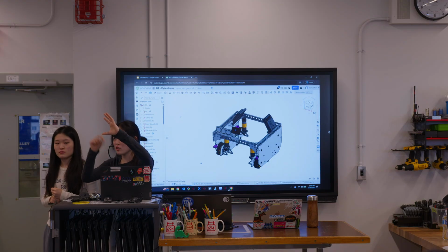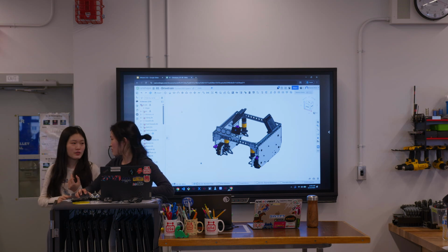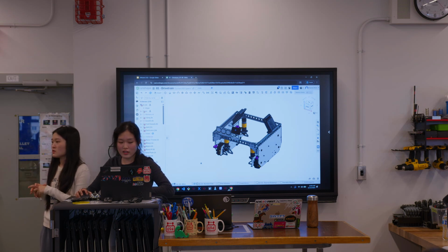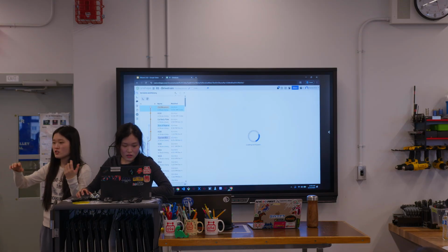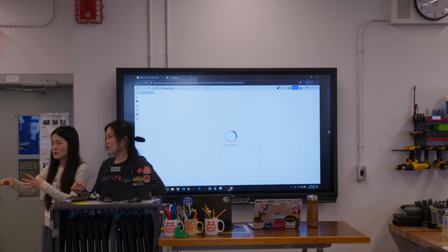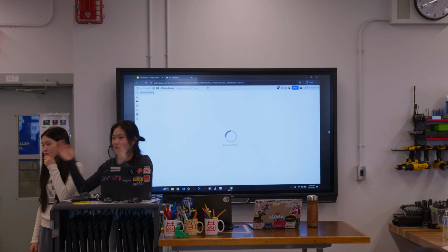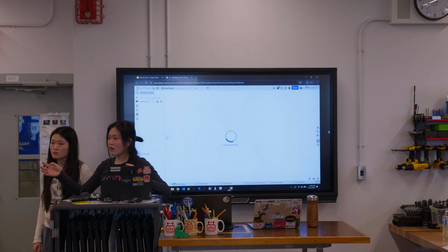So if you delete that, you can always just drag it up and down. But I just make sure to re-add it so not everything's blue. And sometimes we add variables. You could temporarily add a dimension to it. So sometimes I'll do a minimum extension and a maximum extension, and then I type in the extension of how much it needs to be, and then everything adjusts along with it in the part studio.